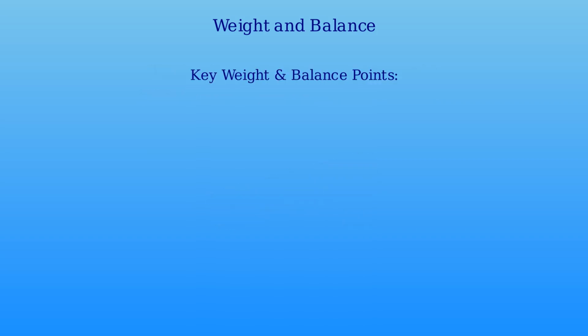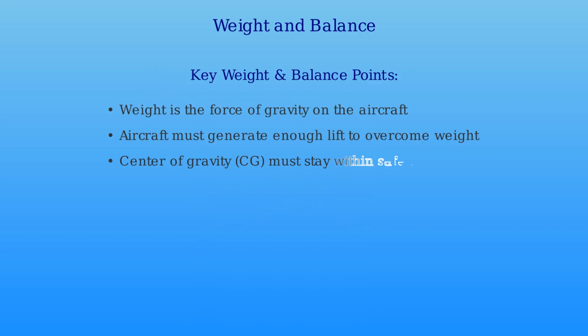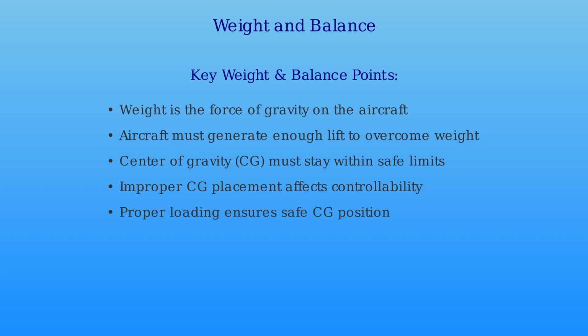To summarize the key points about weight and balance, weight is the force of gravity on the aircraft. The aircraft must generate enough lift to overcome weight. The center of gravity must stay within safe limits. Improper CG placement affects controllability, and proper loading ensures a safe CG position. Understanding weight and balance is critical for safe flight operations.